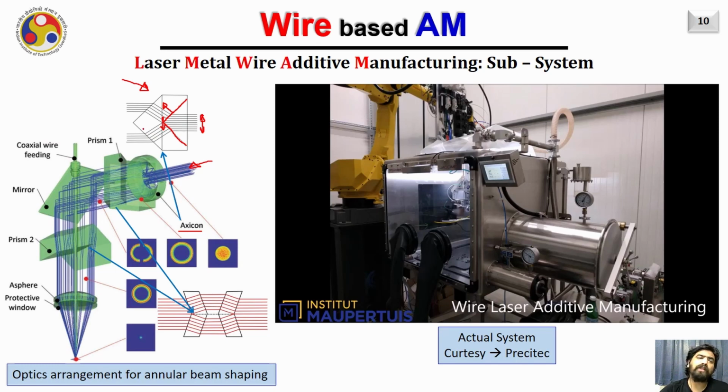As a result, when the laser beam comes out in the air from the lens, again they will become parallel to the original one. So now the beams are parallel to the original one, but they got split into two halves. As a result, you will have a donut shape or annular beam from a solid beam when it passes through the hexagon.